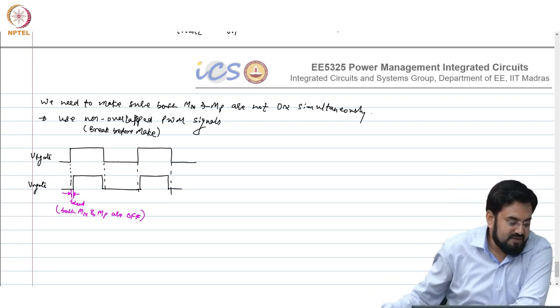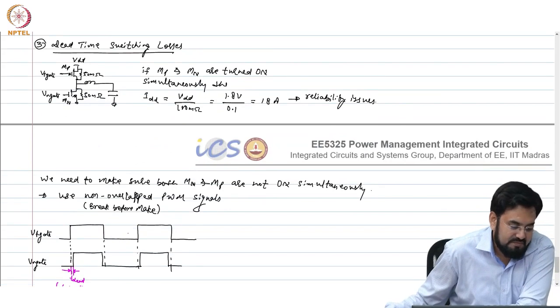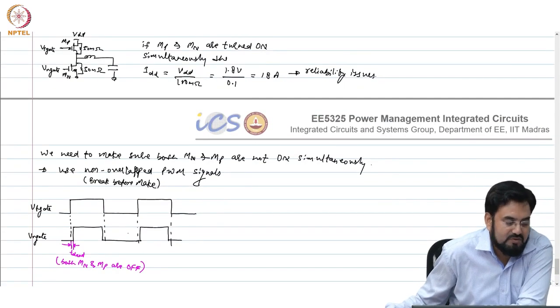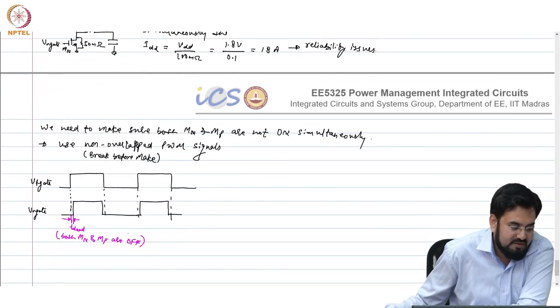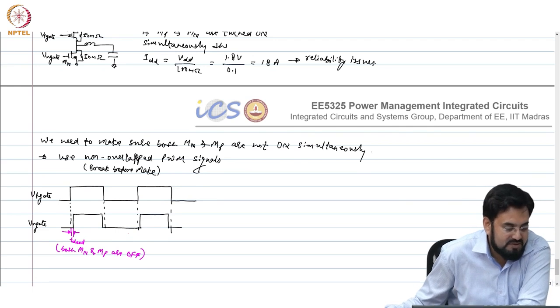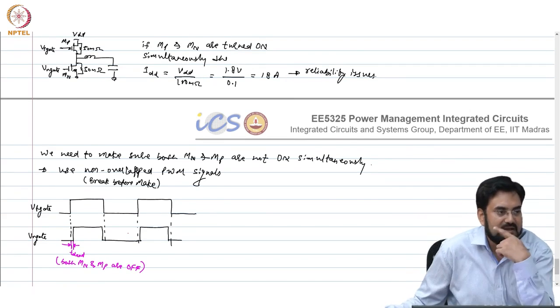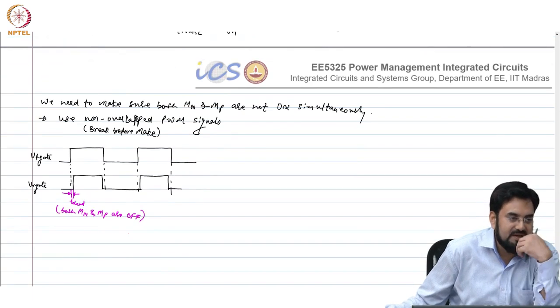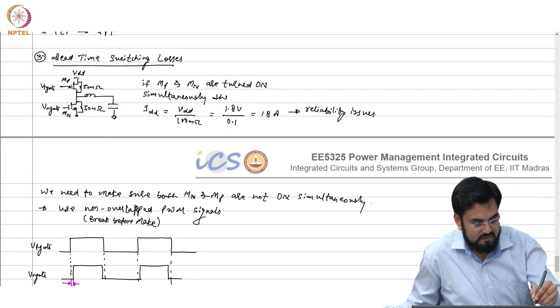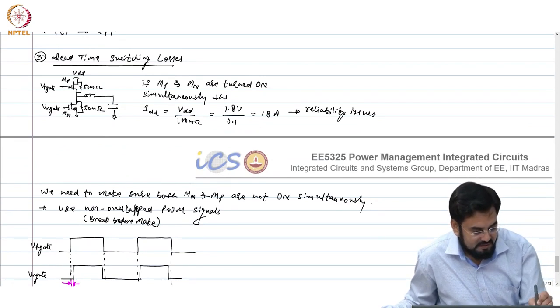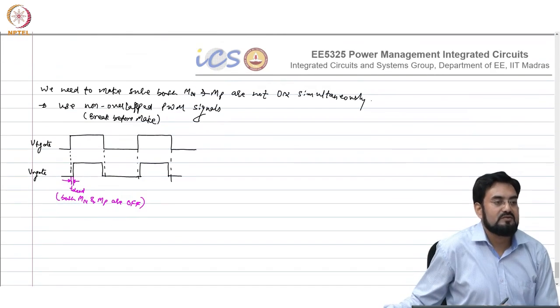Okay. So when your P gate is low, your load current is flowing through PMOS. And if your N gate is high or bottom switch is on, your load current is flowing through NMOS. So now during this time, dead time, both are off. So where is the current going then? So this is your load current. So where will the current go?